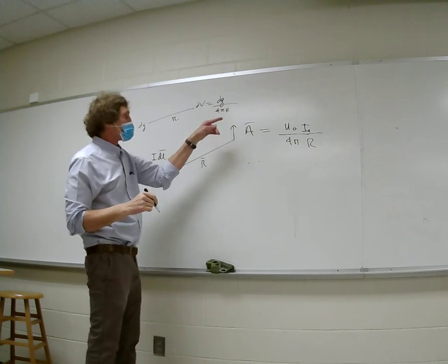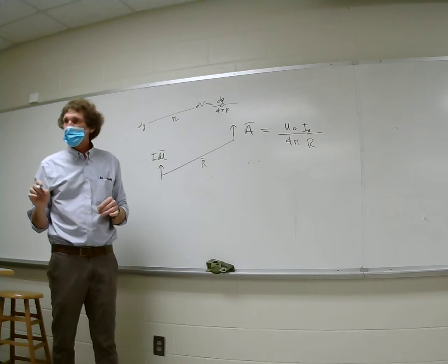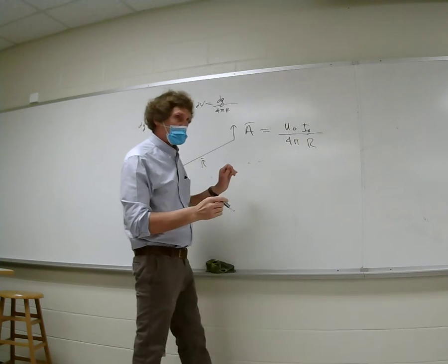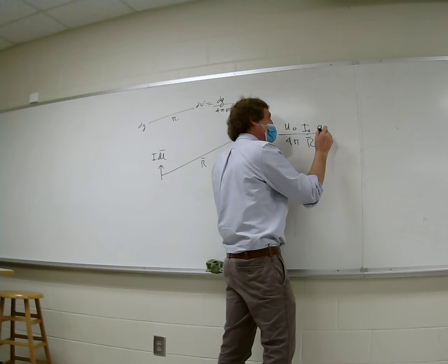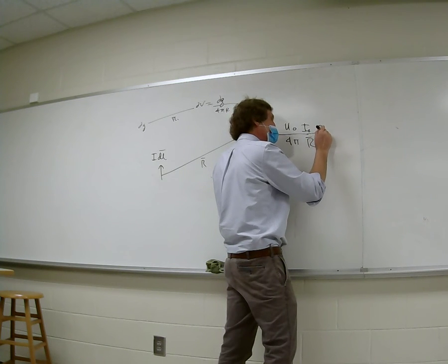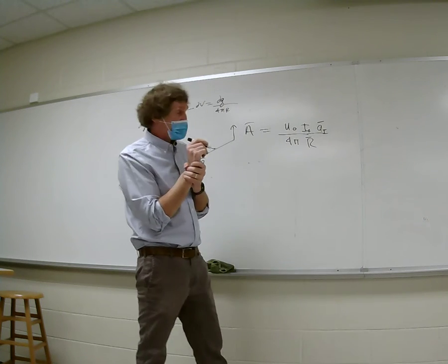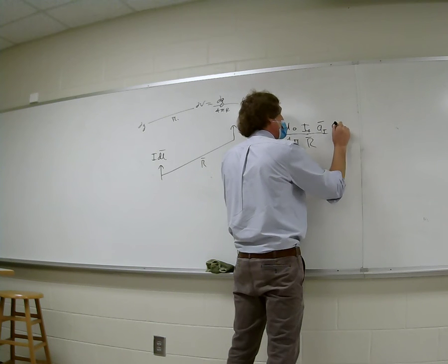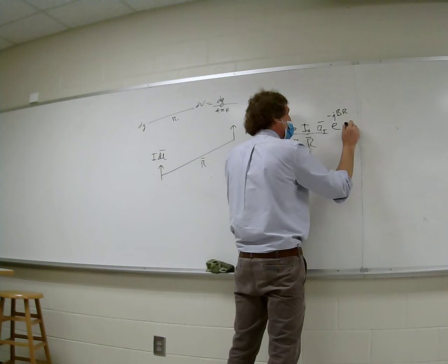It's dq over 4 pi r for voltage. Electric field would have r squared. My bad on that one, okay? And it's over r, and that's the distance here. The vector sense is just A right here, and it's in the current's direction. So it's in the direction of the current is the unit vector there. And it's equal, there's also going to be an e to the minus j beta r, and then it's dl.